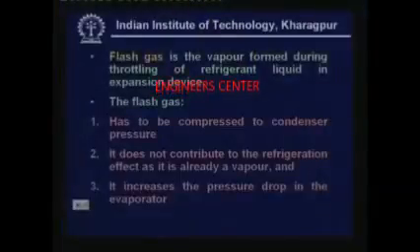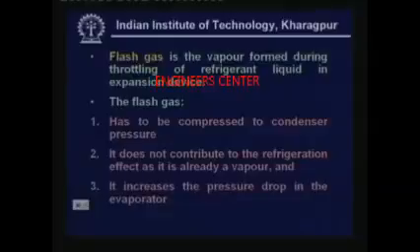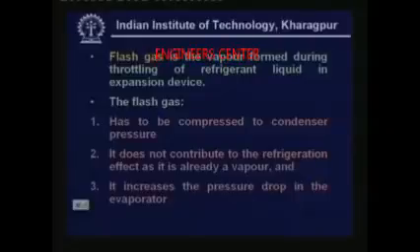And another disadvantage is that it increases the pressure drop in the evaporator. Okay, so these are the problems. Once flash gas has reduced the temperature, it has to be compressed back, it does not contribute to the refrigeration effect, and it increases the pressure drop in the evaporator.